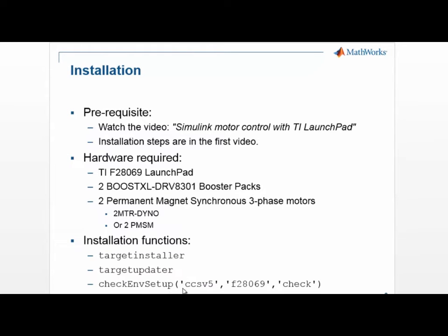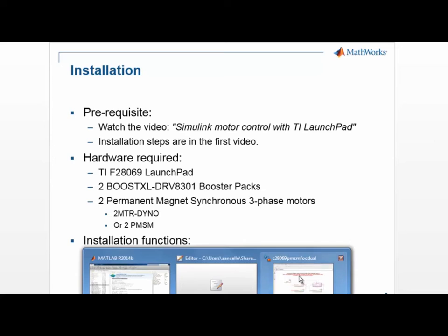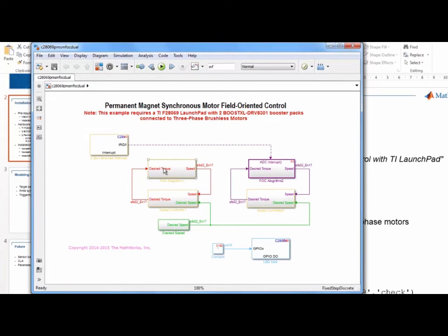So here is what I use to control the two motors. I'm just going to generate code and run it, and then I will go through explanations on how I got there. So I can press that build button. It will generate code for this model. It will invoke the CCS compiler, and it will load the code on the F28069 LaunchPad that I have connected right now to my USB cable. I haven't connected high power yet. Let's wait until we load the code, then we can start the 20 volt to spin the motors.